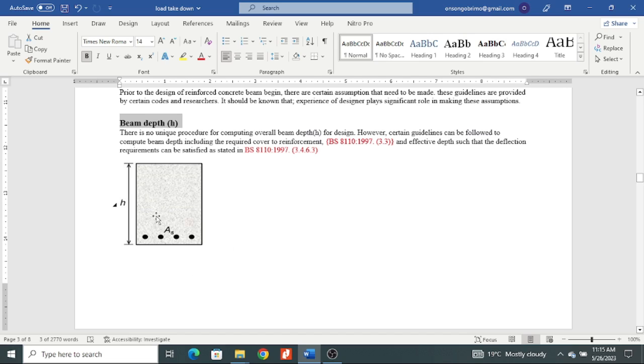Sometimes, though this is a disclaimer, the architect or the developer wants a certain size of the beam spanning for longer sections. And when you design it as a reinforced concrete beam, it is going to fail. So this takes you as the engineer to think of what to do so that that beam can be designed as required. Sometimes you're required to do composite sections where you can do a steel section and then you encase it in concrete, or sometimes you are forced to do things like pre-cambering of your beams, which has been talked about in the Eurocode.